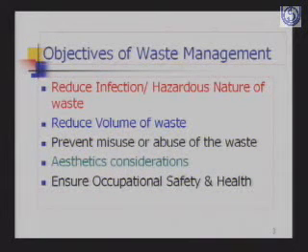What are the objectives of waste management? The first objective is to reduce infection or the hazardous nature of the waste. Second is to reduce the volume of the waste. Then prevent misuse or abuse of the waste. The fourth is aesthetic consideration, and the fifth objective is to ensure occupational safety and health.